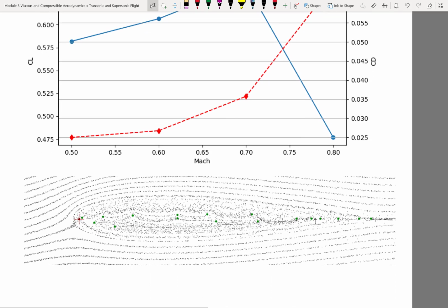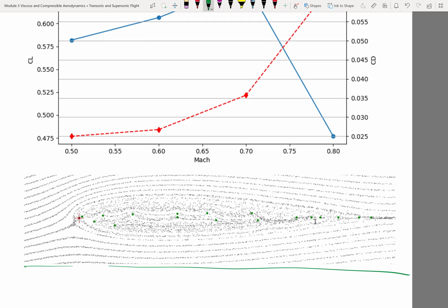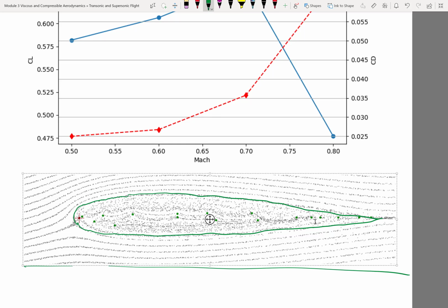So let's look at an incompressible flow field. This is what's coming from the flow builder: the flow around a symmetric airfoil, basically made by placing a bunch of vortices and sources and sinks. So this is the airfoil. Very bad drawing. And let's work out two scenarios. One scenario is that we have a stream tube, let's say this stream tube, that decelerates all the way to the stagnation point.